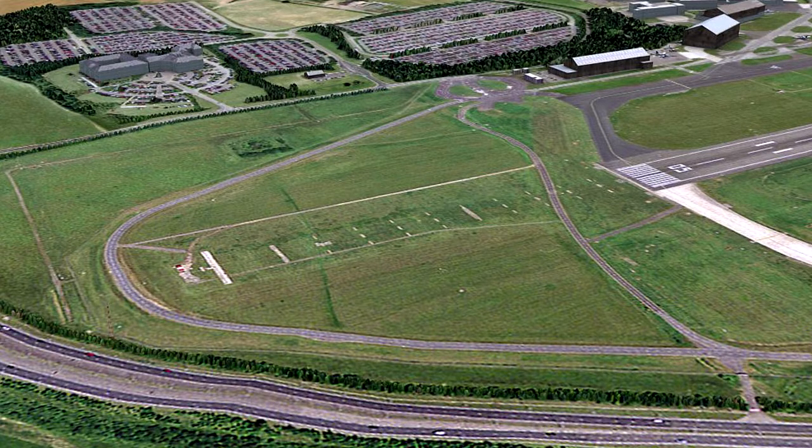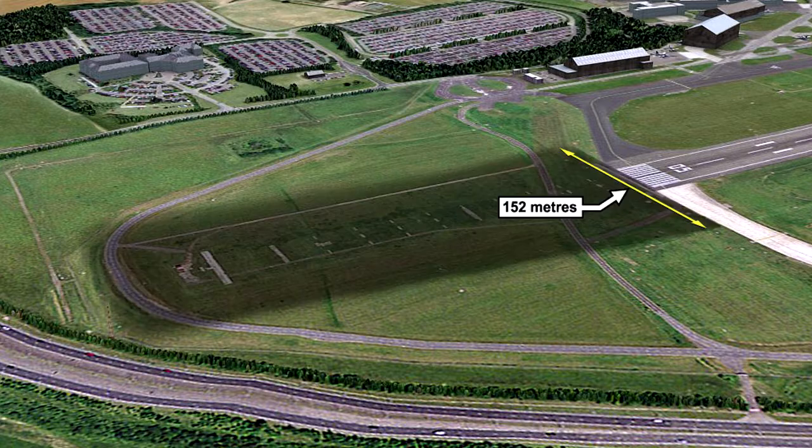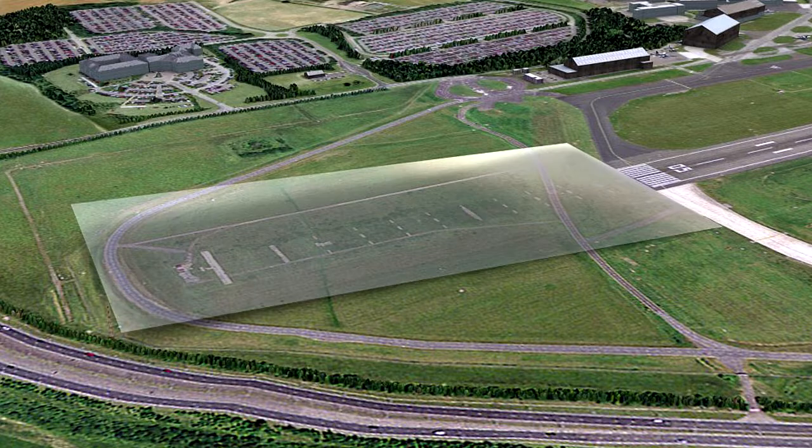There is one other additional type of extension that can be made to a runway. This is called a clearway. A clearway is defined as a rectangular area beyond the end of the TORA, not less than 152 meters wide, centrally located about the extended center line of the runway and under the control of the airport authorities. The clearway is actually the area underneath the clearway plane, which extends from the end of the runway with an upward slope not exceeding 1.25%, above which no obstacle or terrain protrudes.